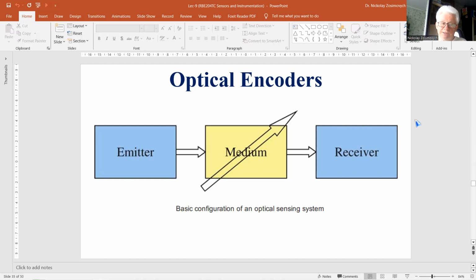They convert, through an optical intermediate, the measurement quantity into a binary signal, representing a binary coded measurement value. Sensor types that belong to this category are optical encoders, designed for measuring linear and angular displacement, optical tachometers, measuring angular speed or the number of revolutions per unit of time, and optical barcode systems for identification purposes.